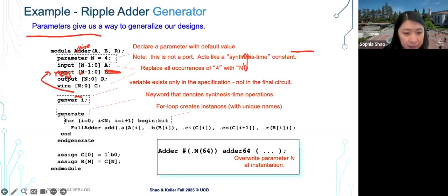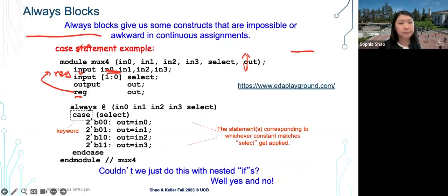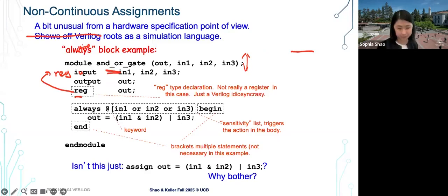Sure, yeah. With the always block, I think that when the synthesizer synthesizes the circuit, the output you write in always will give you a latch, but the components are designed as just logic blocks, logic gates. Why do you think it will give you a latch here? Because it's probably an always block.